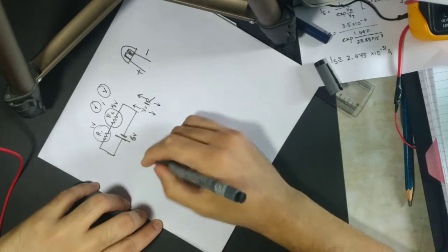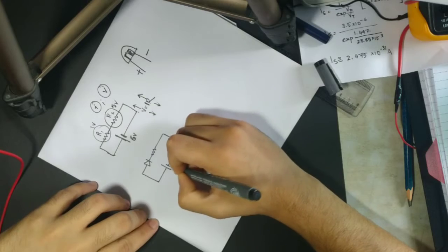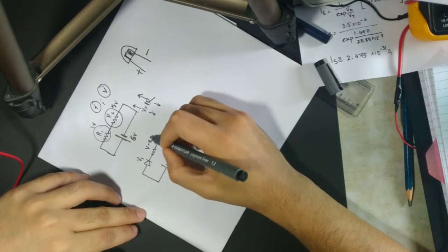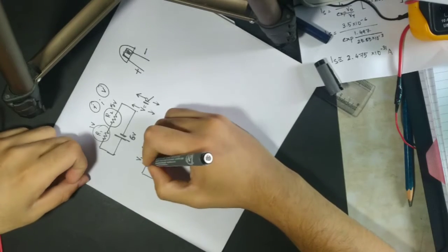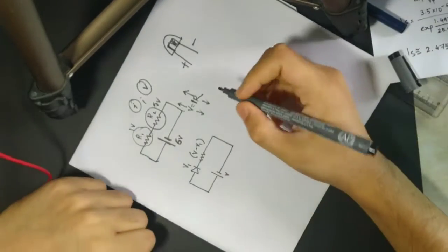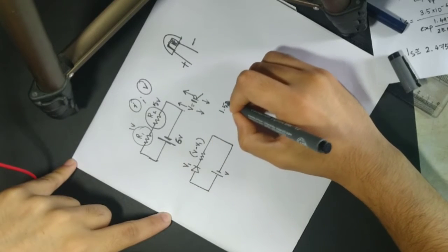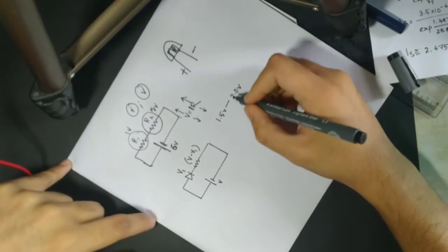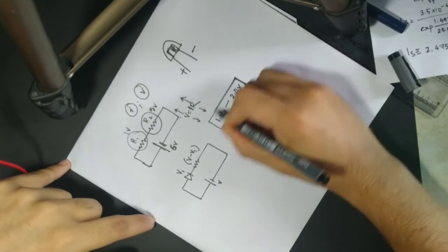The same thing happens with the LED. Now if I connect the LED with a resistance here and a battery of V volts, definitely a voltage will be dropped here, V1, and then V minus V1 will be dropped for this resistance. Now one of the important things with an LED is that the voltage drop through the LED remains rigid. By rigid I mean, practically you can see that the voltage drop across an LED will always be between 1.5 volts to 2.0 volts. It can vary depending on the color of the LED, but mostly I use red. So for the red LED, the voltage drop will be between these two values.